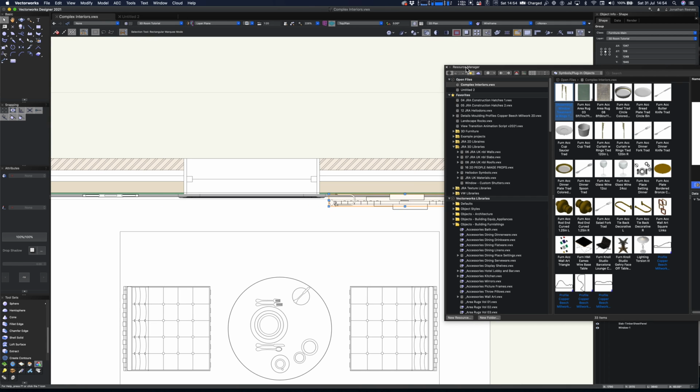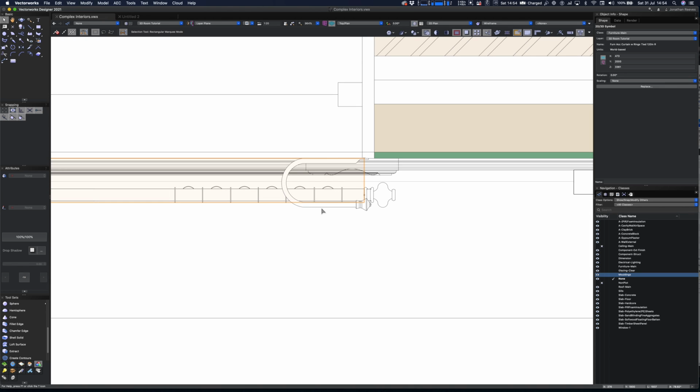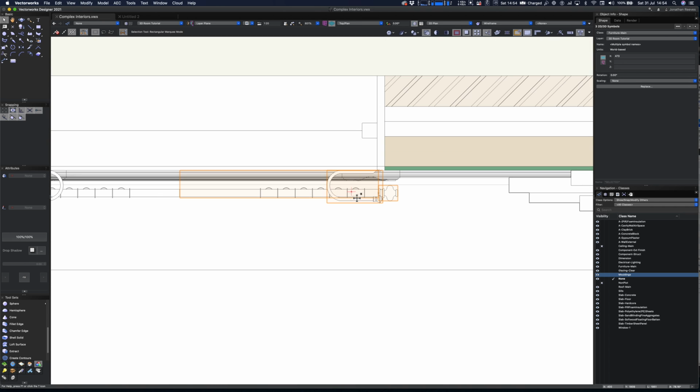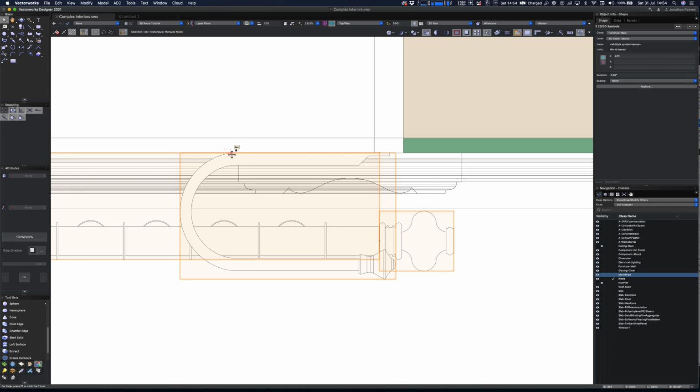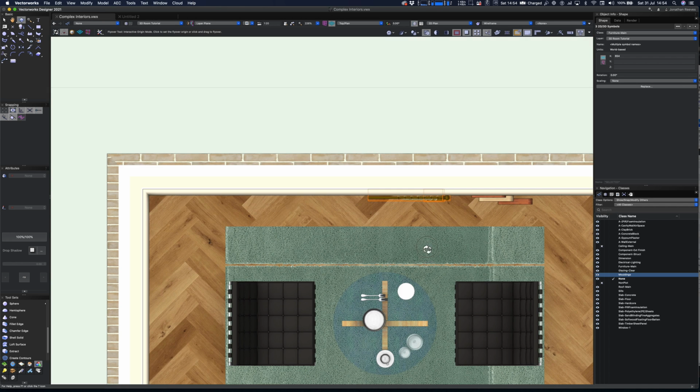And you can see the really nice thing with the curtains that you get from Vectorworks libraries is, if I can just grab them, let's move them across, they actually look great in 2D as well as 3D. What you can do though, you can ungroup them. And this is great because obviously it means that you can get them to fit different sizes. So I'm just going to drag this one across to the correct position. There we go. And then let's delete the other one.